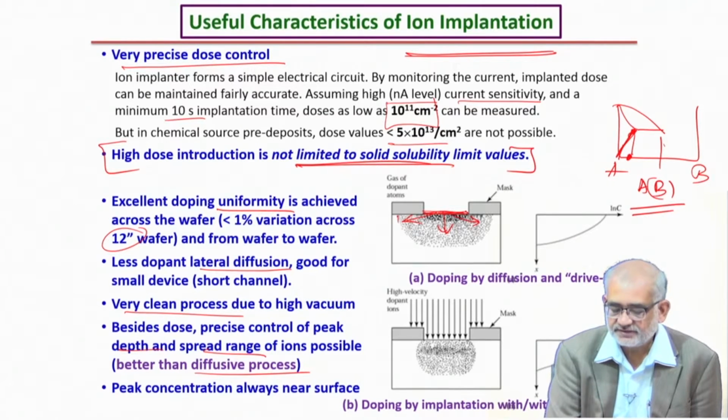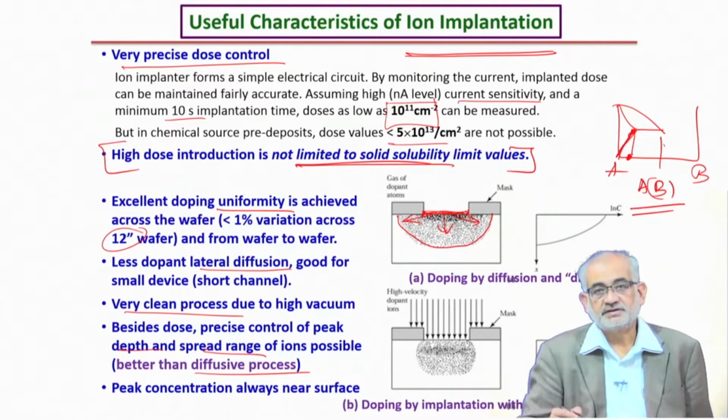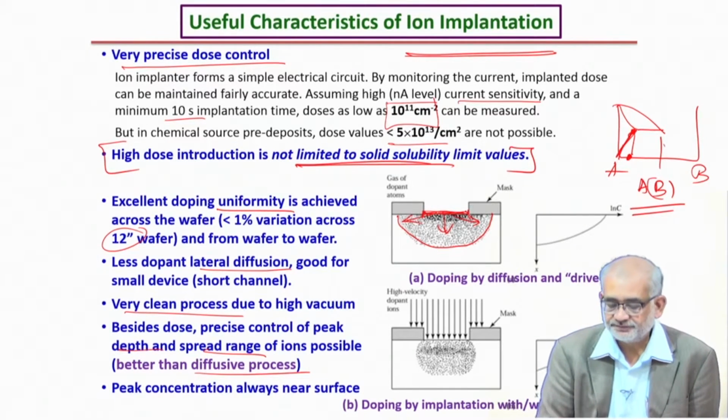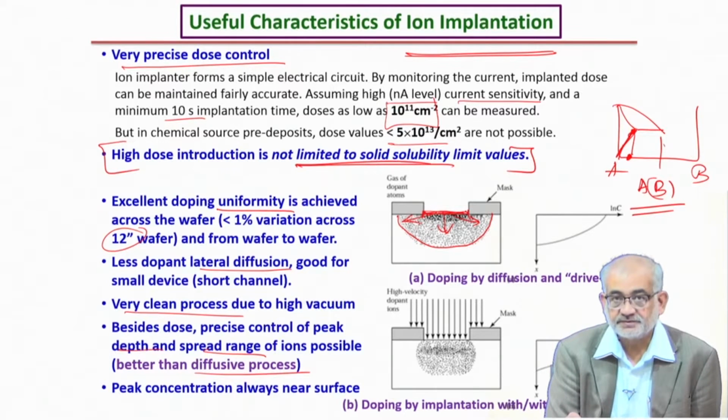And as a result, the final diffusion profile that you create would be much wider than the typical gate that you have allowed. So the precision of the performance of the device that you create may be suspect, because the diffusion profile ideally should have been confined to this region, but that's not happening.